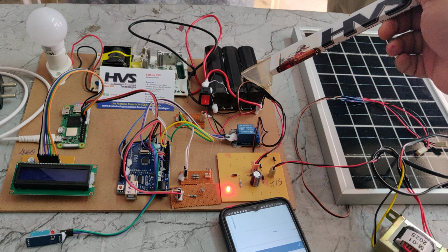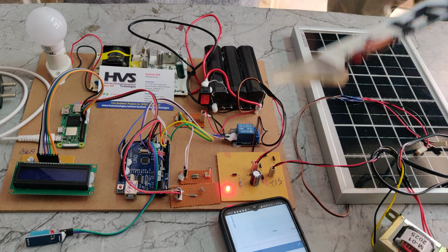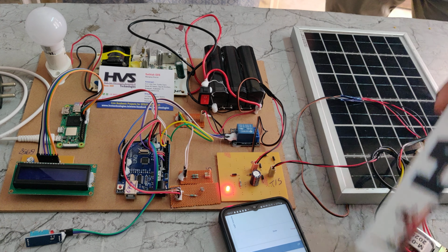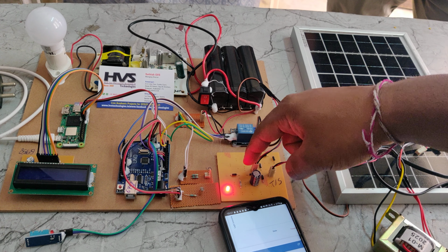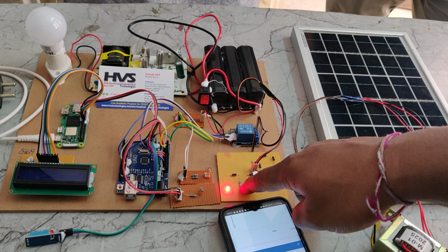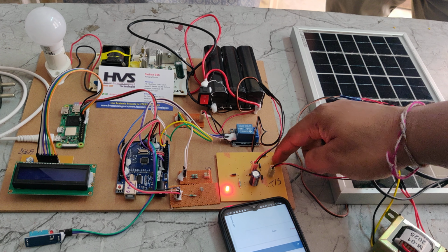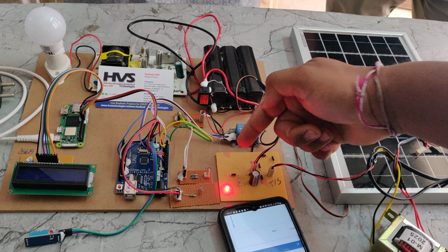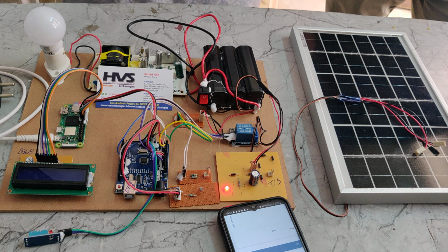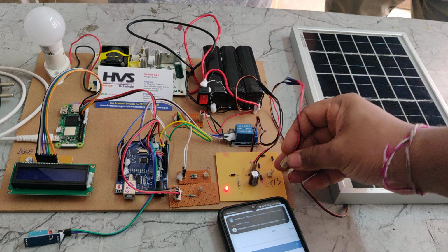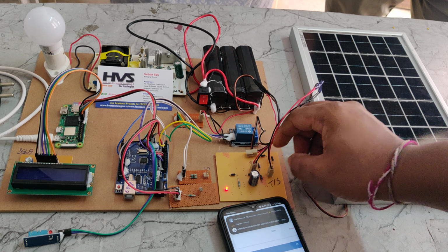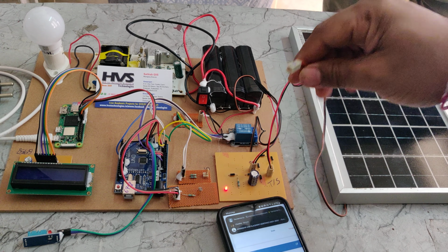Whenever the battery is fully charged, these 2 diodes will block the current flow from the battery to the transformer. So that's for protection purposes, and this is the LED indication along with the current limiting resistor. So here when we provide the AC input from the transformer, these 4 diodes will act as an AC to pulsating DC converter. But when we are demonstrating the main project, we need to disconnect the transformer and connect the 2 pins at this T/S slots.